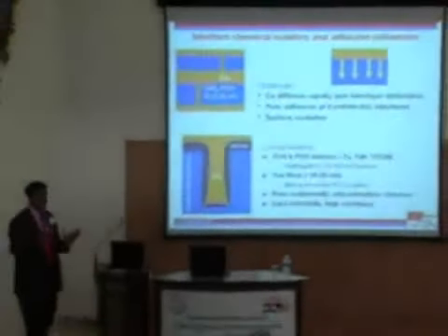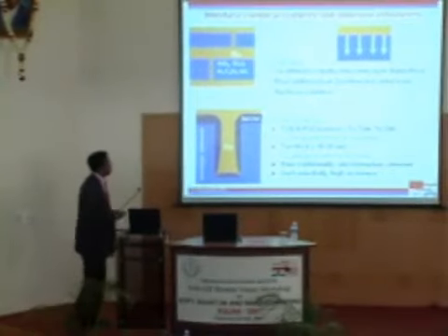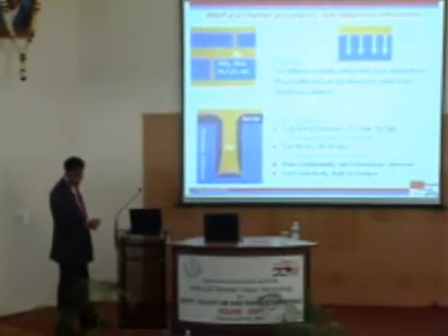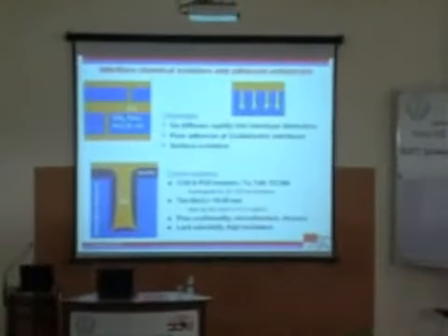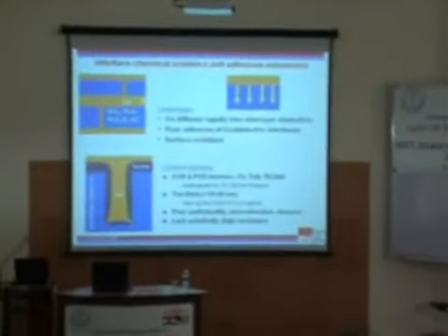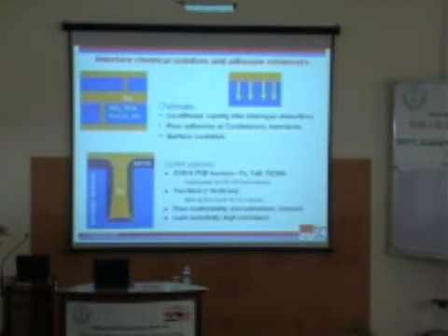Okay? And of course, structural integrity needs to be preserved no matter what. It can't crumble. So I'm going to take the simple example in the current microelectronics device paradigm, and also the nano paradigm, wherein copper integration with low dielectric constant materials is a problem, because copper diffuses very quickly into the adjacent layer, and also it doesn't stick very well.